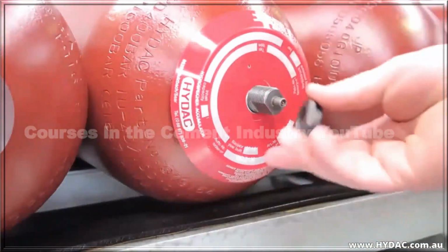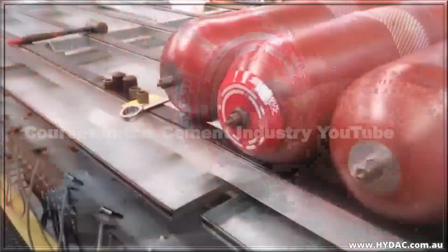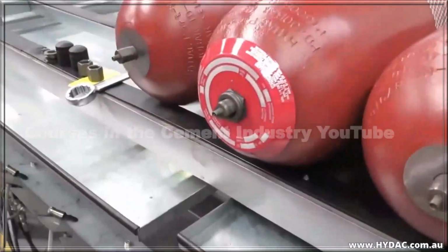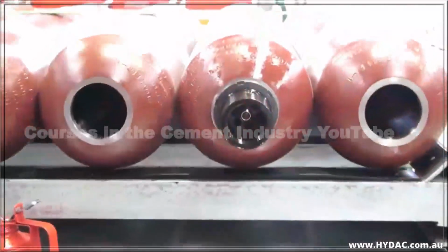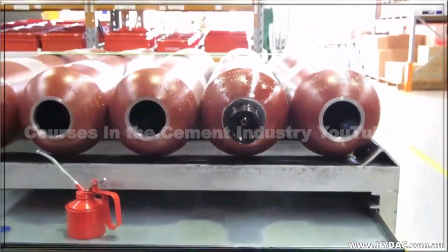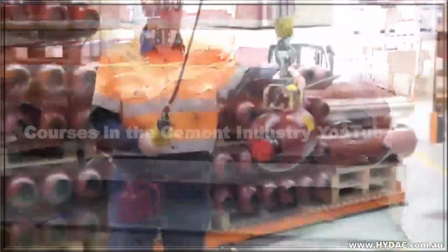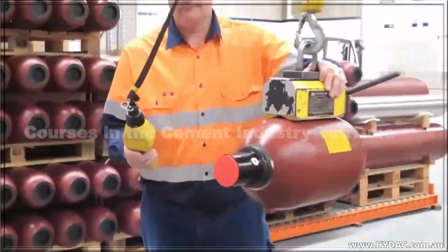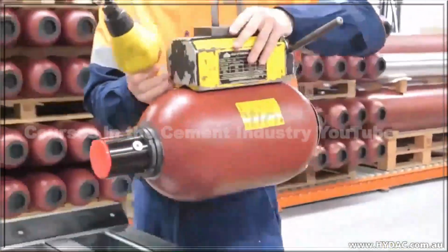On no account must any welding, soldering, or any mechanical work be carried out on the accumulator shell. Work on systems employing hydraulic accumulators must only be carried out once the pressure in the fluid and/or the gas have been released.